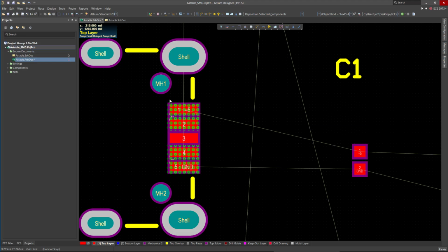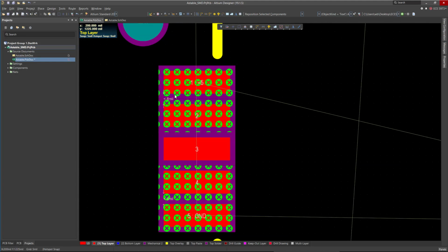Now, why do we see a design rule error in here? Because the spacing between the pads for these surface mount components is much smaller than the design rules we set for the through hole parts. Now, when we covered the layout and schematic and the projects, all the parameters, design rules, electrical rules we set for the first project are still in there.